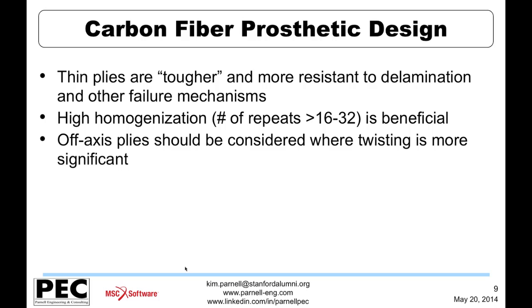These particular components are predominantly unidirectional composites. So that means that the fiber direction, they have a single fiber in them, a single strong axis, and then these plies here are oriented for these components all in the 0 degree direction, or along the length of the foot or the heel member. That's the direction of primary bending.